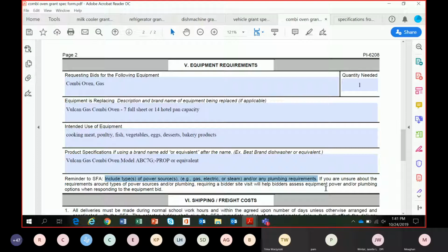A little bit touch about the combis. What I know about those also is that the output from the combi, as well as this is the same for dish machines, some municipalities require that you have water tempering on the unit so that the water going into the sewer system is not at a very high temperature, which can really affect their whole system. So you want to make sure that you're checking on that component for both dish machines and for combi ovens, if there is a drain tempering system needed on the piece of equipment for the municipality codes.